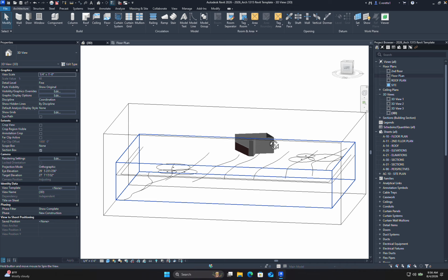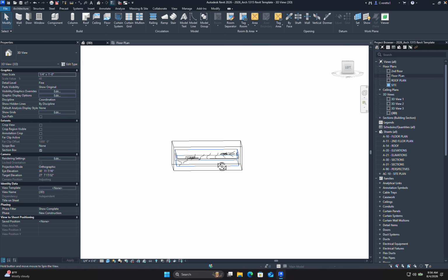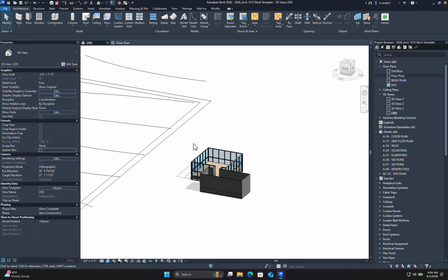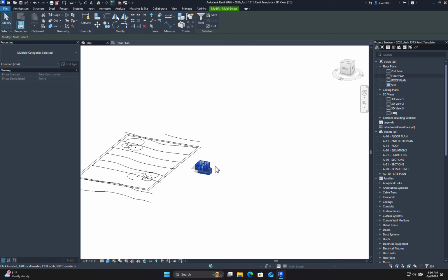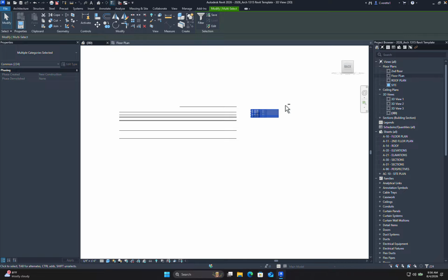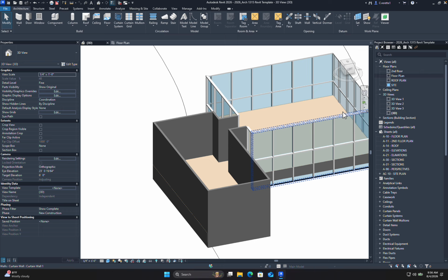It looks like it kept my old piece, so let's get rid of that. Get out of here. And I may have to go find my piece real quick. Right now, in my three-dimensional view, I have my section box on, which basically is a box of section. I'll unclick that real quick. Oh, there it is. Right. So what is nice is you can move this entire piece, but it is a little bit more difficult. So in my case, let's just scoot that over using my arrow keys. My bad. To be fair, I could just move the topography too, right? But in my case, as you can see, it essentially turned that instantly into a 3D model.